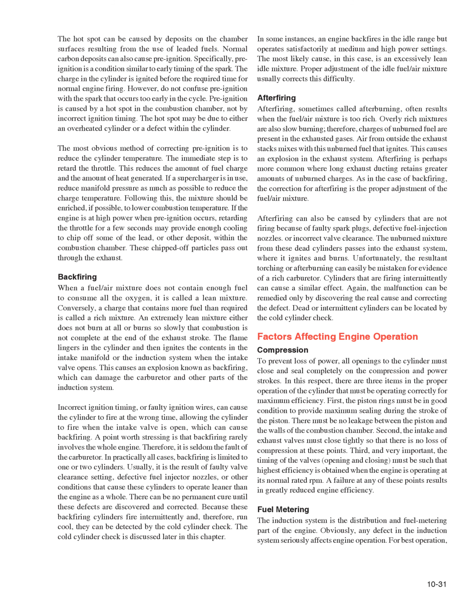The flame lingers in the cylinder and then ignites the contents in the intake manifold or the induction system when the intake valve opens. This causes an explosion known as backfiring, which can damage the carburetor and other parts of the induction system. Incorrect ignition timing, or faulty ignition wires, can cause the cylinder to fire at the wrong time, allowing the cylinder to fire when the intake valve is open, which can cause backfiring.